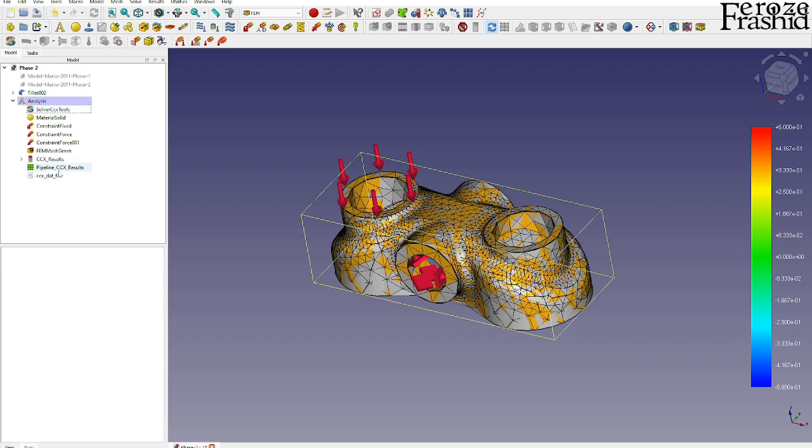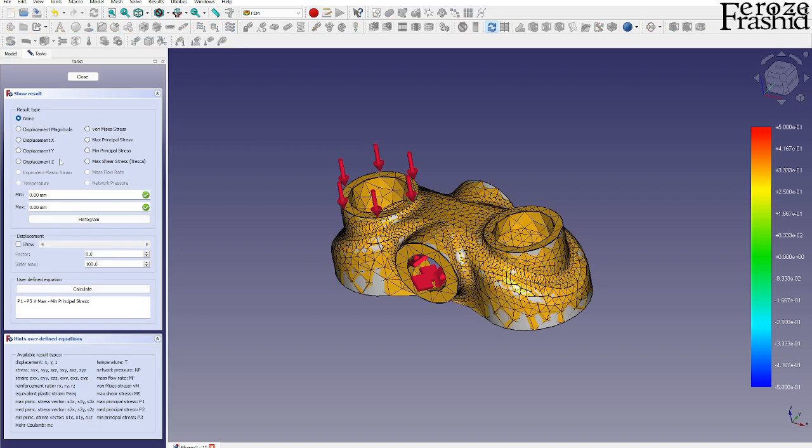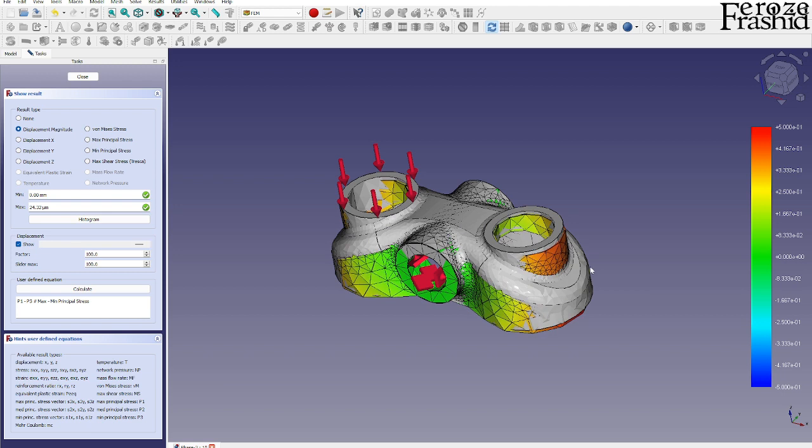Okay, let's take a look at the results and see if this load is there. We will see from the displacement. Looks like it's there. The maximum displacement is 24 micrometers, which is very negligible. Looks like it's a well-built model for this load at least. I want to look at the displacement and see how it is moving downward here, which tells me the load is there in the calculation. It's just not showing up. So the bug is preventing the display, but not the work.